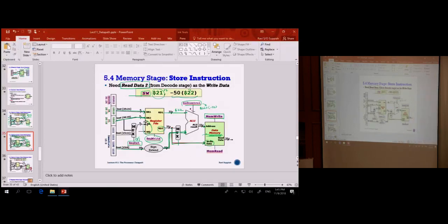I've got two questions. This is the dumb one. What's the one with the ratio thing? Like 20 ratio 60? No, it's not a ratio, it's bits. 25 to 21 means bit 25 to bit 21. Your instruction is 32 bits, correct? You know the first 6 bits is the opcode, correct? So the first 6 bits is bit 31 to bit 26. Then the next 5 bits, the next 5 bits. So that is actually the bit location.